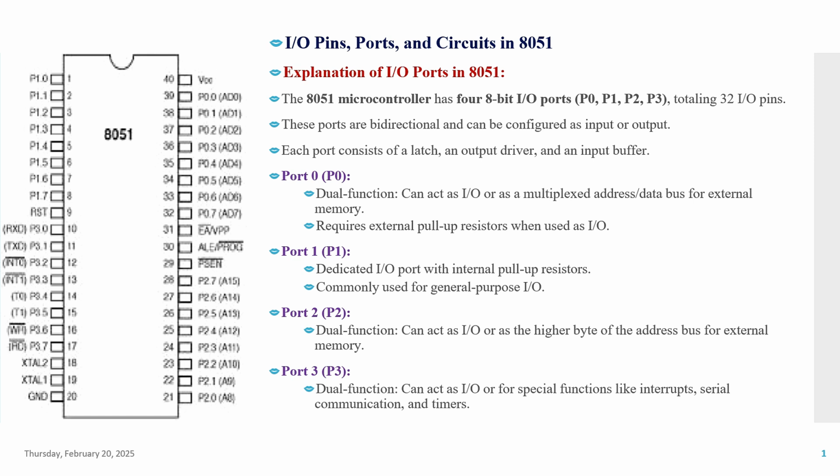Port 0 has dual functionality: it acts as input-output and also serves as the multiplexed address-data bus for external memory. Port 1 is a dedicated input-output port equipped with internal pull-up resistors, and it is commonly used for general purpose input-output applications.